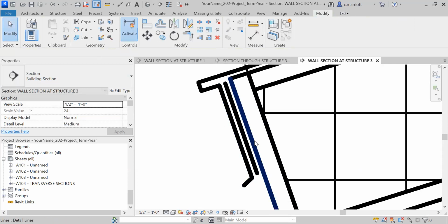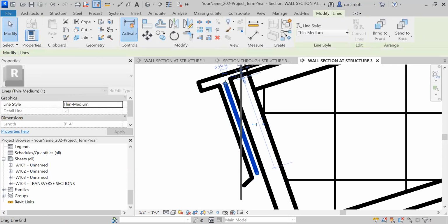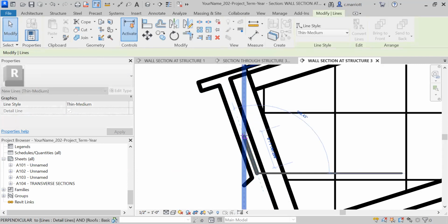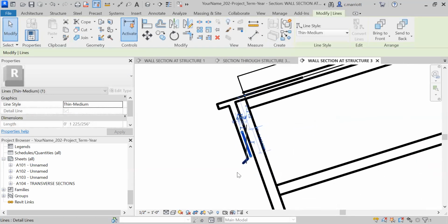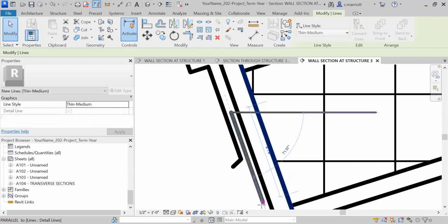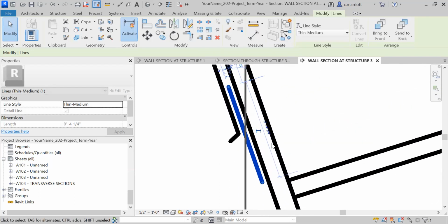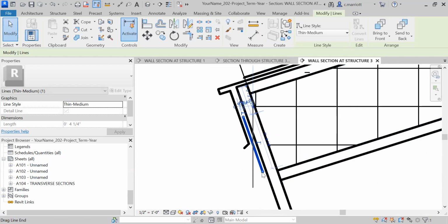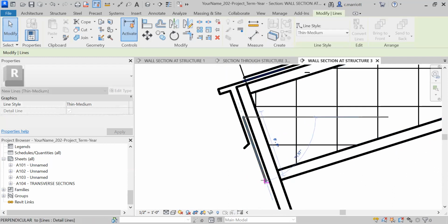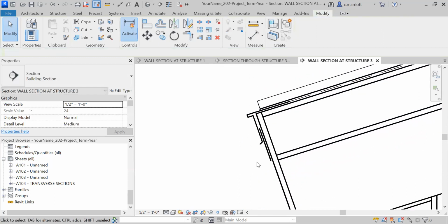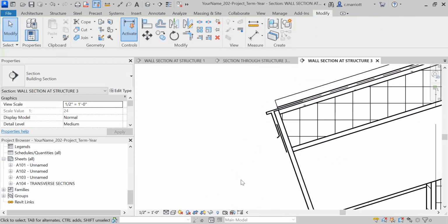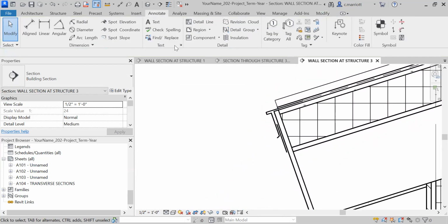these lines here. This is going to be part of the gutter assembly, and I'm going to bring it down a little bit. And which is the dimension there, say 4 1/4. Let's bring it down to 5 inches. And we'll make a kind of custom shape for this gutter.